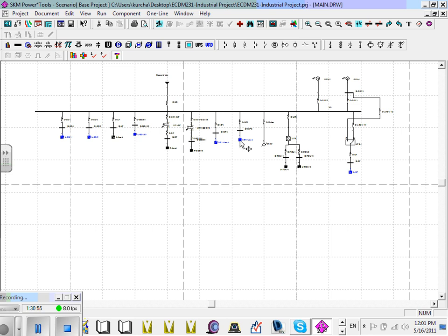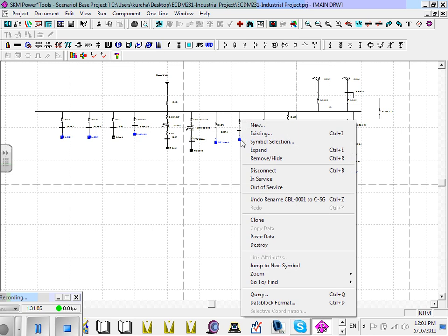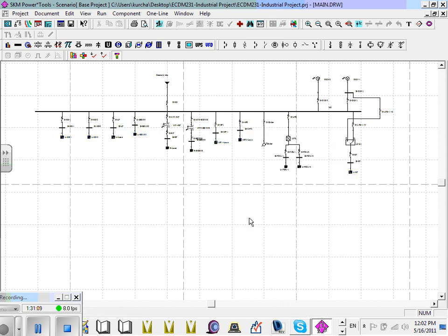Now right click. There's another load. There's a chiller. The chiller, we loaded the chiller. We already put the load for the chiller. Yeah. Avoid that one. Thank you. Right click on it and paste data. Now all your loads, they say 50 kVA. Now I know they are not 50. You guys are going to go get the loads from your load calculation, plug them in there. But the reason why I put the 50, so it runs the analysis for us. Okay?